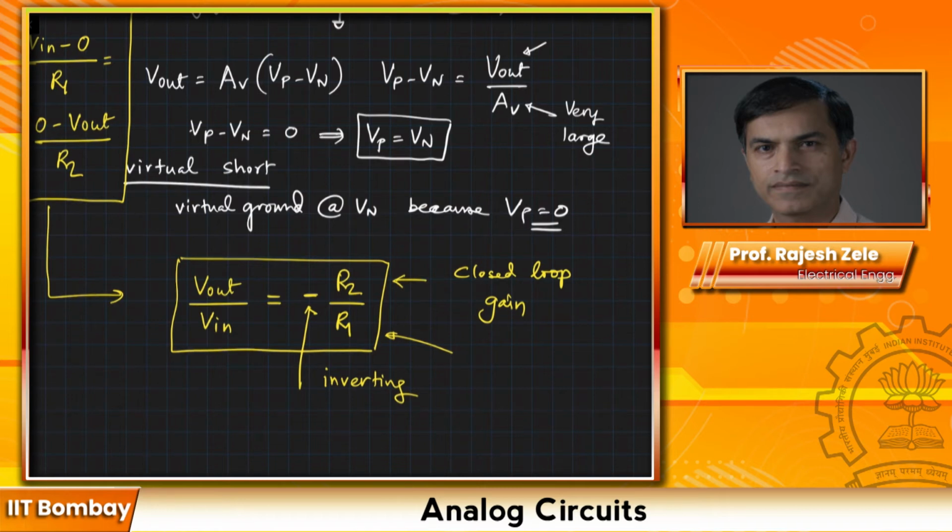So the absolute values of R1 and R2 may change, however, they will move together on each chip if they are physically next to each other. So what happens then is we get a very accurate gain, even though each component, for example R1, may vary plus minus 15% and R2 may vary plus minus 15% from its desired value, and AV can vary a lot.